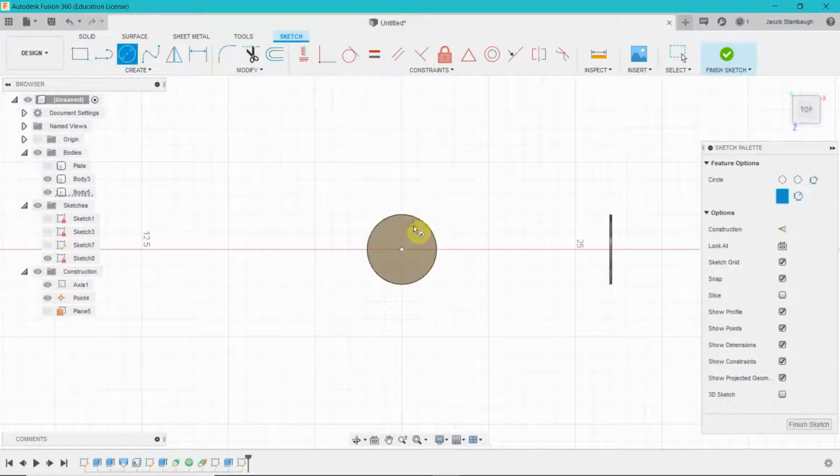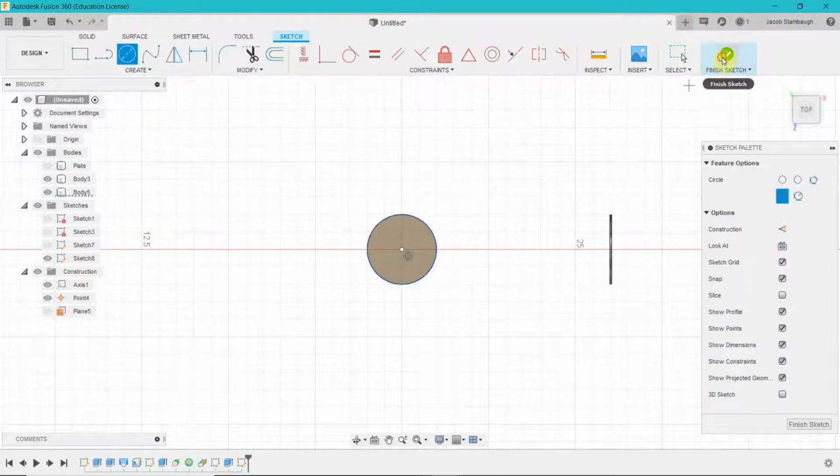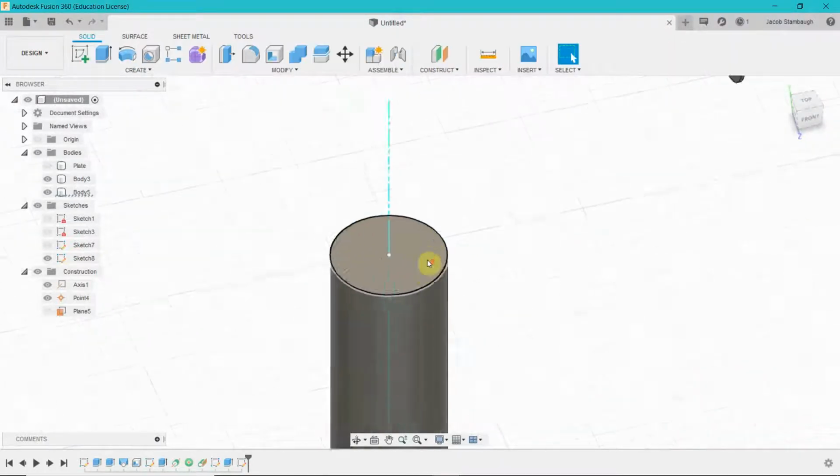I'm doing this because I can't extrude some, then put a gap, and then extrude again using the same geometry. So I'm going to draw the same exact geometry onto this and offset that to extrude. If I just do that, now we have another.